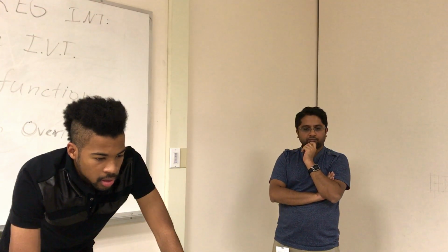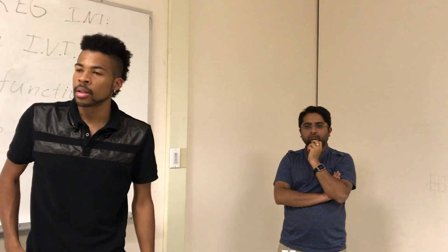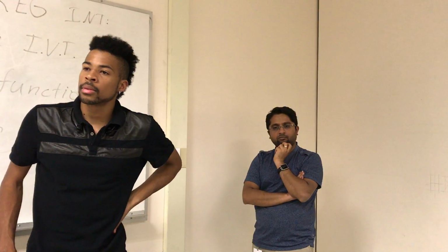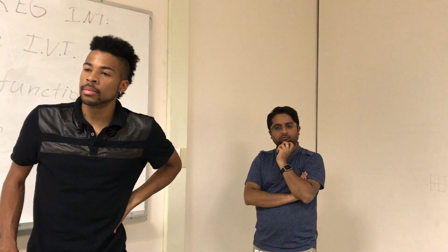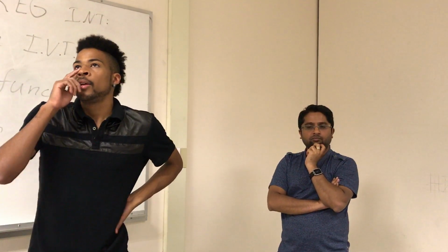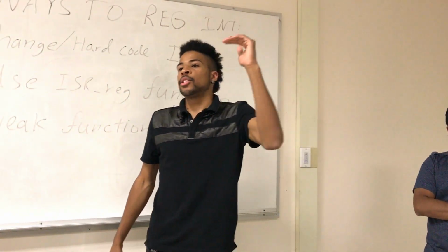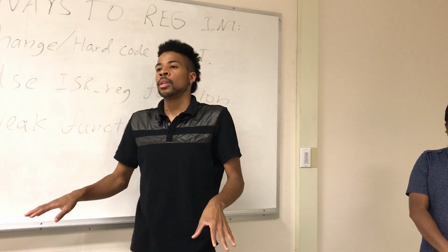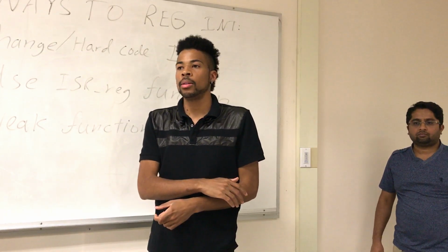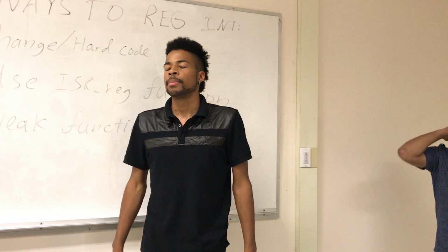Interesting. Okay. See the interrupt, it does have the configuration for port 0 and port 2 for interrupts. But when you go up to the pin select registers, you saw the one that says external interrupt, right? Actually, there's a note in, I think, chapter 6 that says when you have EINT3, it's shared with GPIOs. So there is a particular pin that can be EINT3, but it's also shared with all other GPIOs as well. So it does a lot of different things.